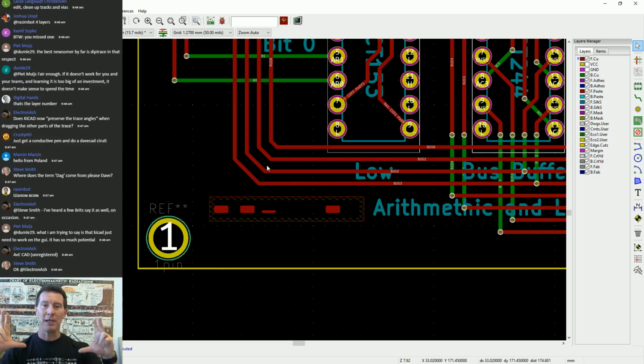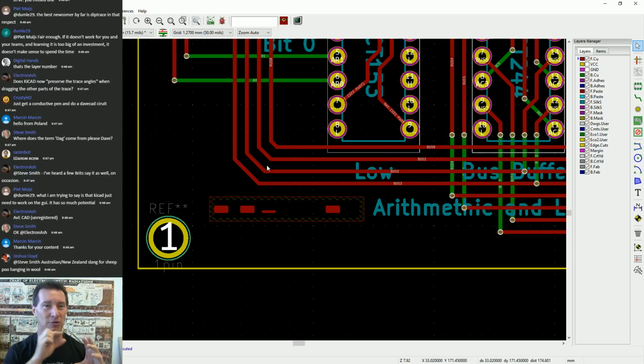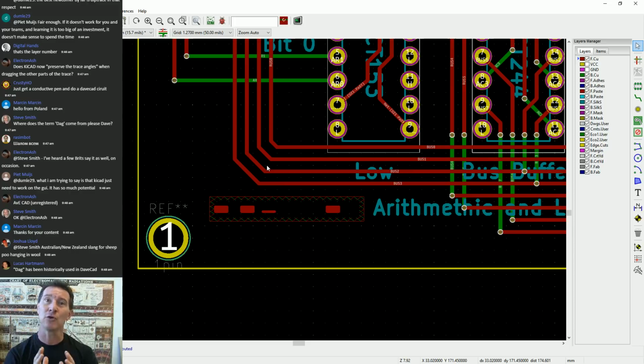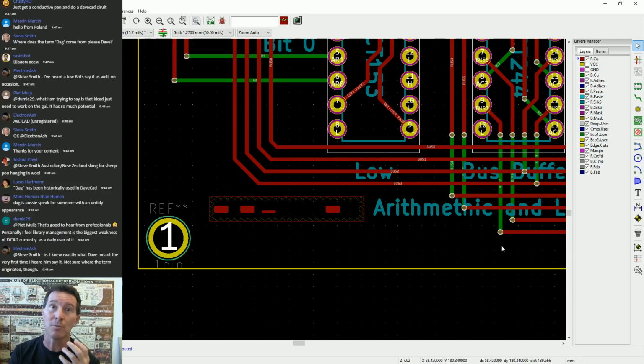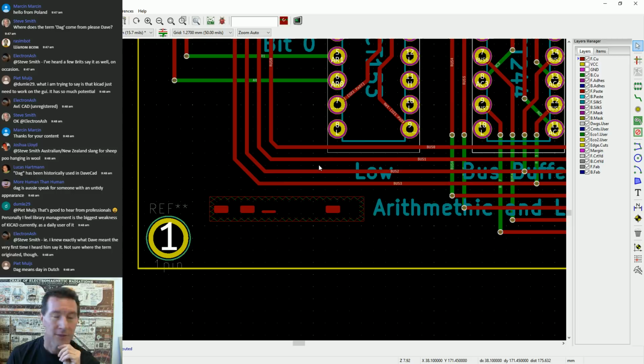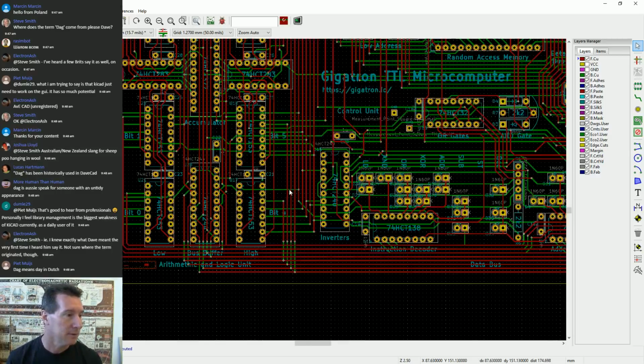Especially if you've got a big, large, complex board where everything's really dense, with really thin traces and really fine-pitched stuff that needs really good alignment, like big 2000 pin BGAs that need critical alignment on the solder mask, then a test coupon is absolutely vital. So on a professional board, you would do that. That's just something that you'd do.